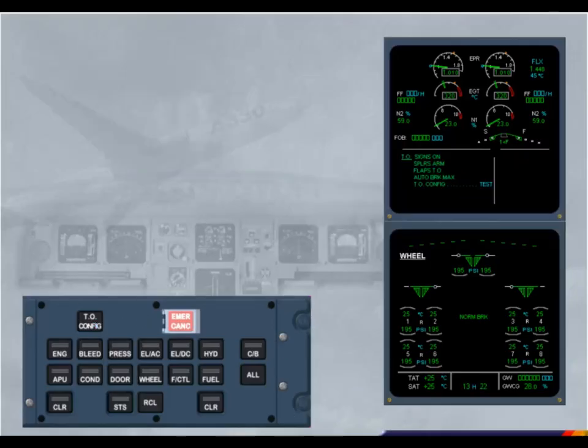By selecting the takeoff configuration key, the ECAM system simulates the application of takeoff power. If the aircraft is not in a takeoff configuration, for example flaps not in the correct configuration, then an ECAM warning or caution will be triggered. Provided ECAM detects that the aircraft is in a normal configuration, then the takeoff configuration memo changes to normal. Observe that there are no blue action lines left on the engine warning display.